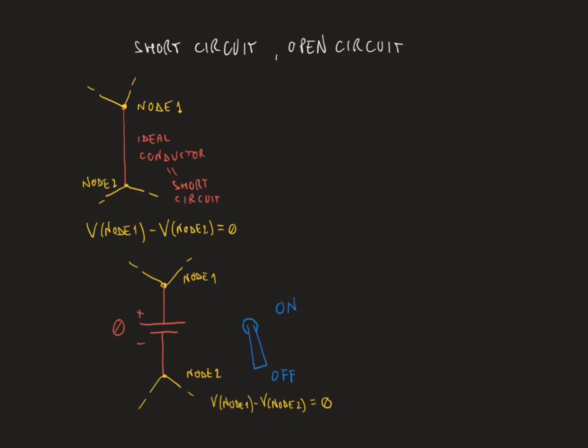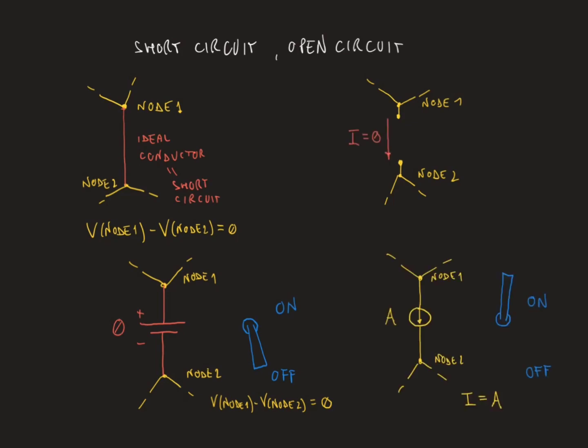When instead I describe the operation of an ideal current source when it is switched off, I use the expression open circuit. By open circuit, we mean the absence of an electrical path between two nodes in a circuit. No current can flow from one node to another if there is no path between them. Actually, switching a current source off means exactly reducing to zero the current flowing between the two nodes connected by the current source itself.